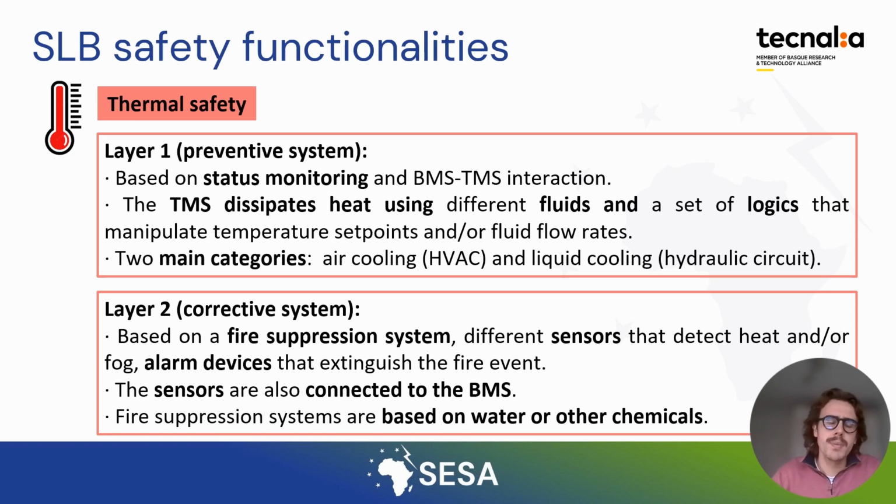The second thermal management layer is a corrective system, so it would be acting on the system based on the fire suppression system, different sensors to detect heat or fog, and some alarm devices to warn of this fire event. These sensors are also connected to the battery management system. The fire suppression system is based on different fluids like water or other chemicals.